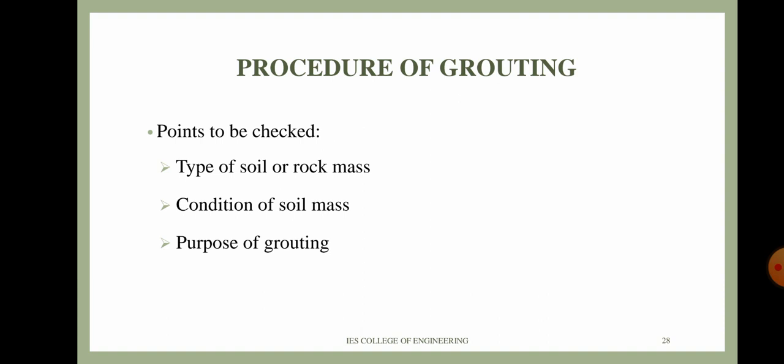The grouting procedure has to be mainly considered. There are different points to be checked before moving on with grouting: the type of soil or rock mass should be identified, the soil condition should be checked, and the purpose of grouting should be known.